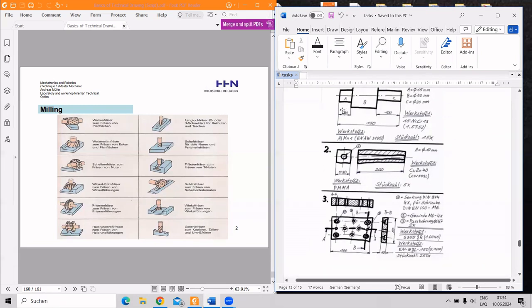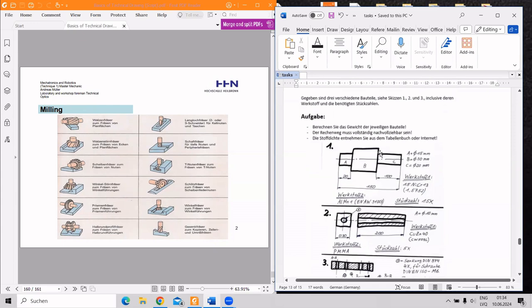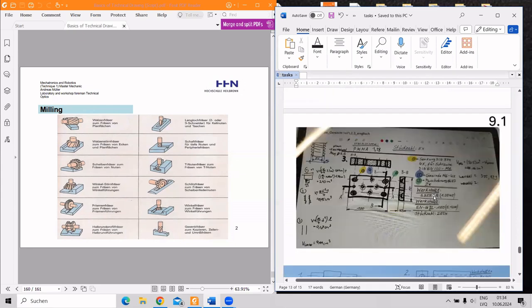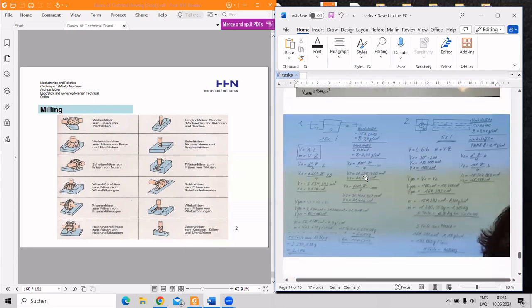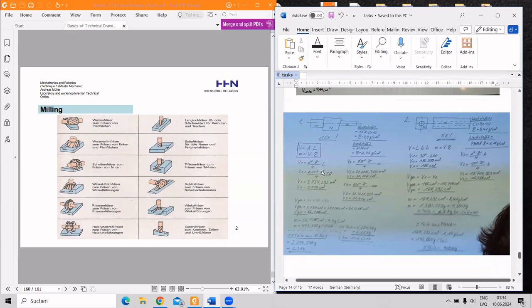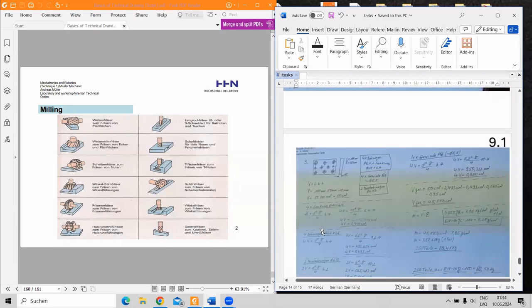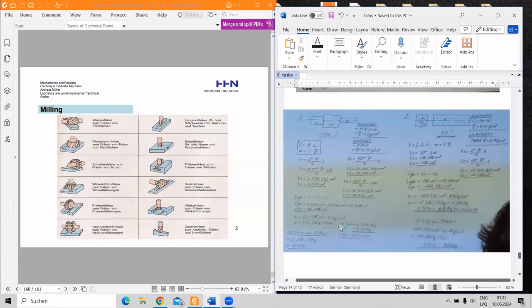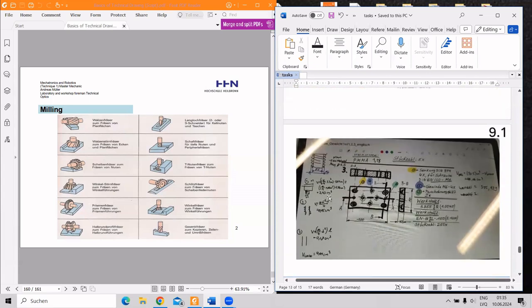Just decompose each part into simple structures, as the first two, for instance, into 3 cylinders, and just calculate it. So as written here in the complex way, we mainly use the formula that the mass is equal to volume times density. Usually the main problem is to calculate the volume correctly.